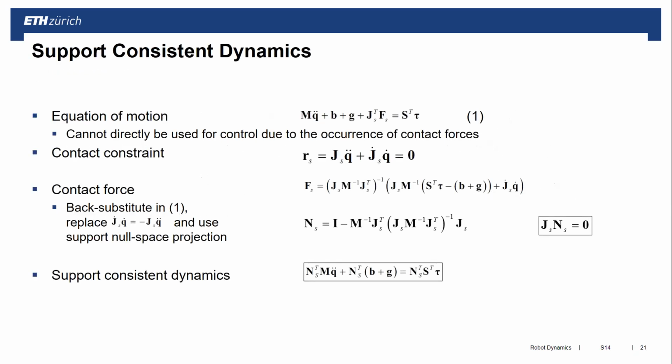So what I can do is I can take this constraint, and I know this constraint must be valid, and I can then solve from this constraint, given the dynamics equations of motion with this external force, for the external force. So that tells me if these constraints should be active, you need to apply this amount of external force to the system.